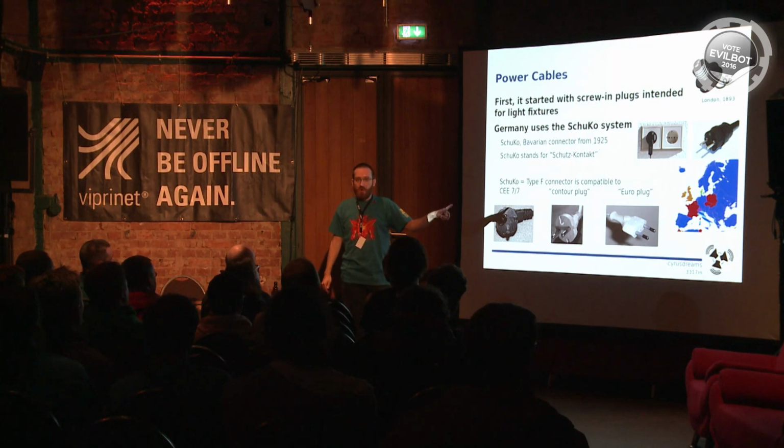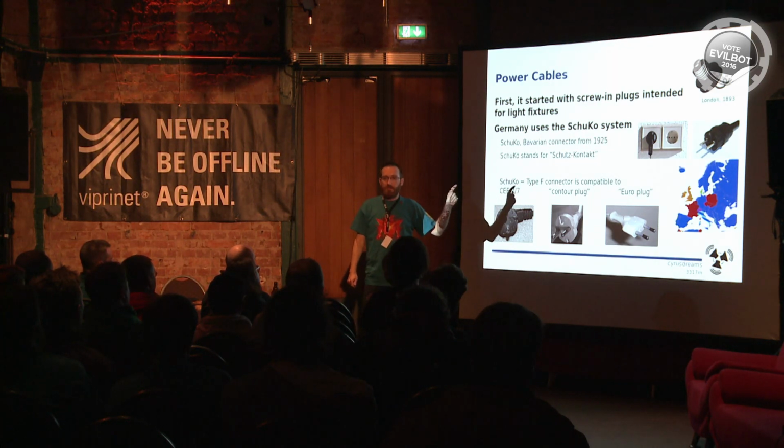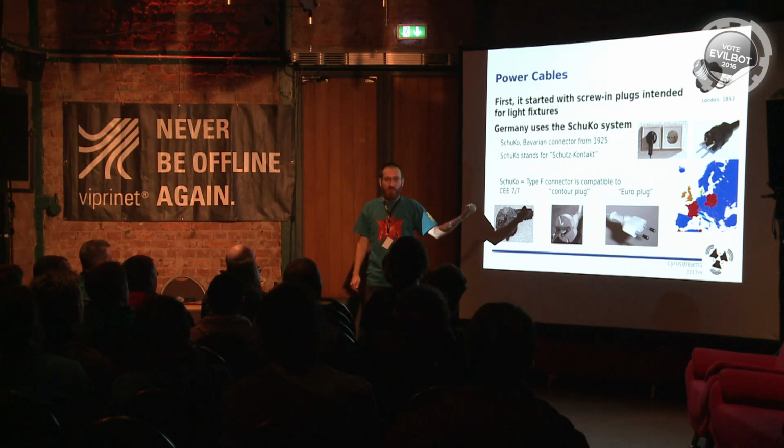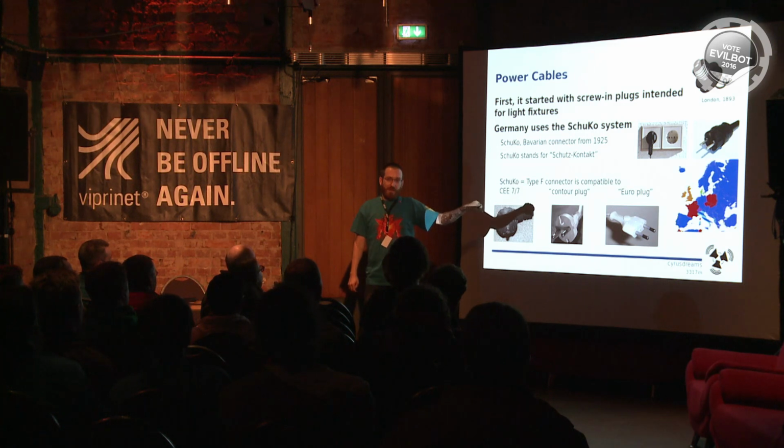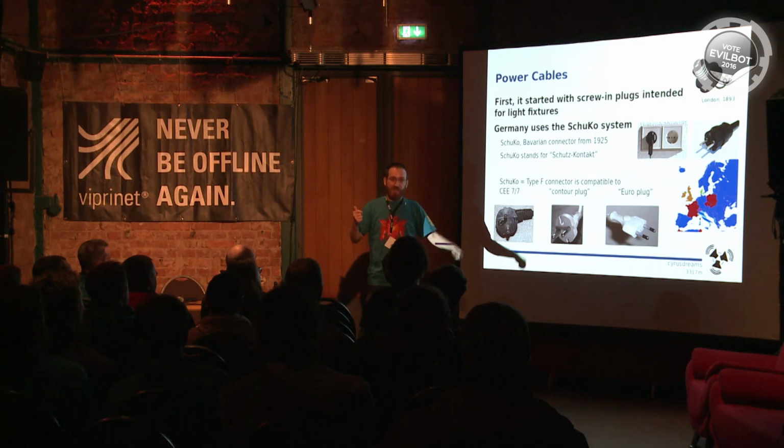One thing to note for people that come from the British Isles and everywhere where they have connectors that cannot be plugged in reverse, that includes France. In Germany, this connector, you can plug it in both ways. If you have a lamp fixture, don't unscrew your bulb when the connector is inside the wall, because the Edison screw on the outside could get live. It's a 50-50 chance if it's live on the outside or live on the center pin.